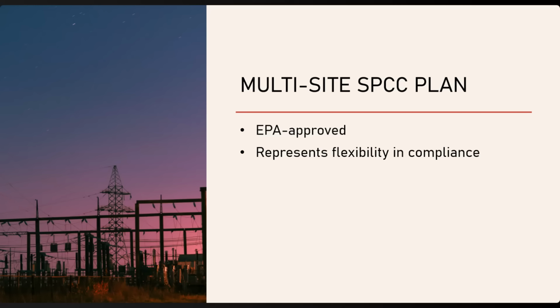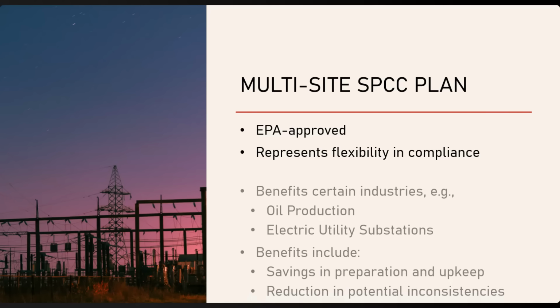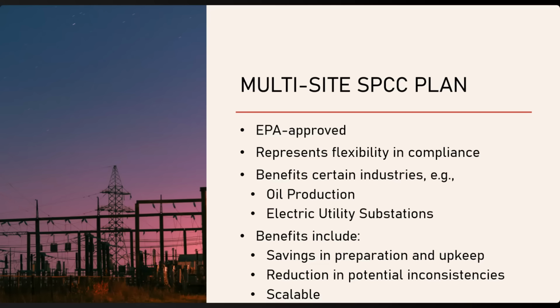Unlike the tiered plan regulation, this is not a special multi-site regulation, but stems from the rule's flexibility in defining what is a facility. In the case of the multi-site plan, a facility may be considered a general description of individual facilities that share common oil container characteristics and spill prevention measures.